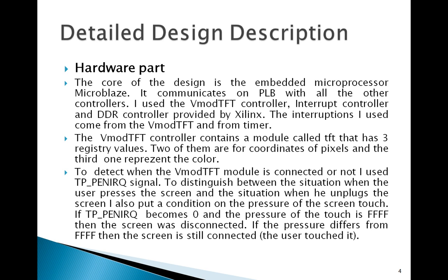The core of the design is the embedded microprocessor MicroBlaze. It communicates on the PLB with all the other controllers. I use the VmodTFT controller, interrupt controller, and DDR controller provided by Xilinx. The interruptions I used came from the VmodTFT and from the timer. The VmodTFT controller contains a module called TFT that has three registers. Two of them are for the coordinates of pixels, and the third one represents the color.